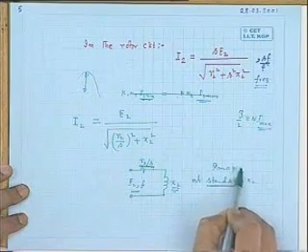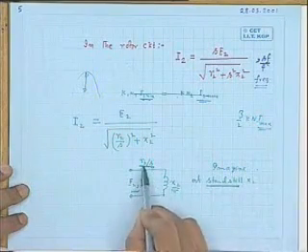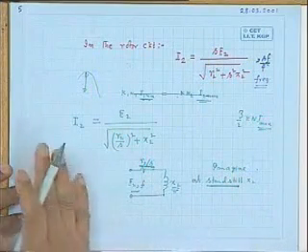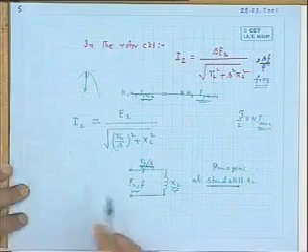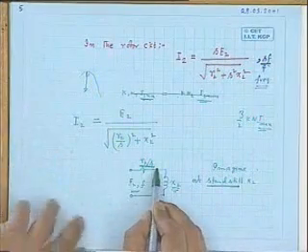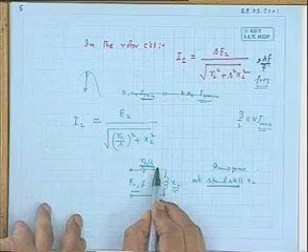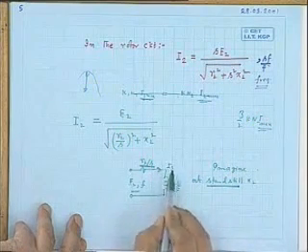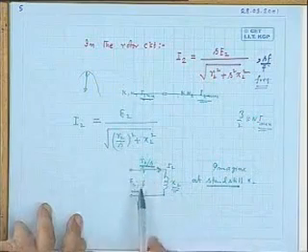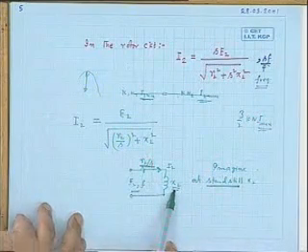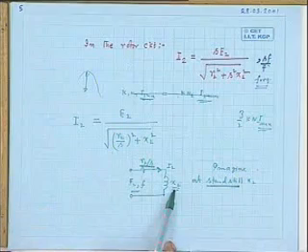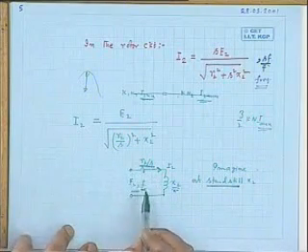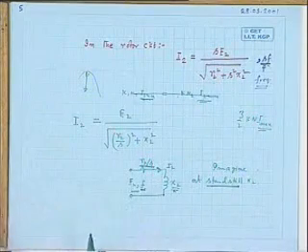And in this conceptual, imagined machine, imagine a rotor whose standstill impedance is like this, and the stator is energized with the usual voltage. At that time, what will be the magnitude of the current in this imagined machine's rotor? Same I2, because it is E2 by square root of (R2 by S) whole square plus X2 square. What will be the frequency of that current? F.